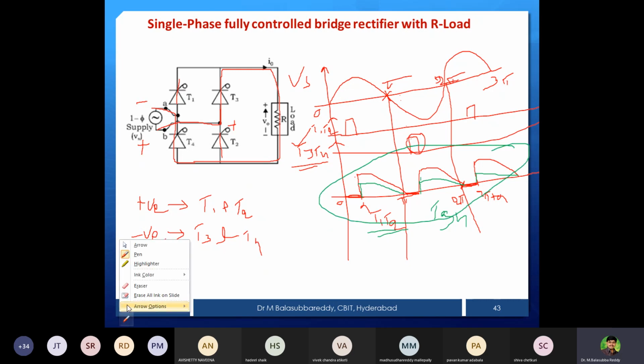Then what I can do, our expression is the same. So if the voltage waveform is the same, we can easily make it an output voltage expression. How will you write the voltage expression now? For this, again there are 2 pulses in the output, that is 2 by 2 pi, and then you can write it as V out or VDC for R load.